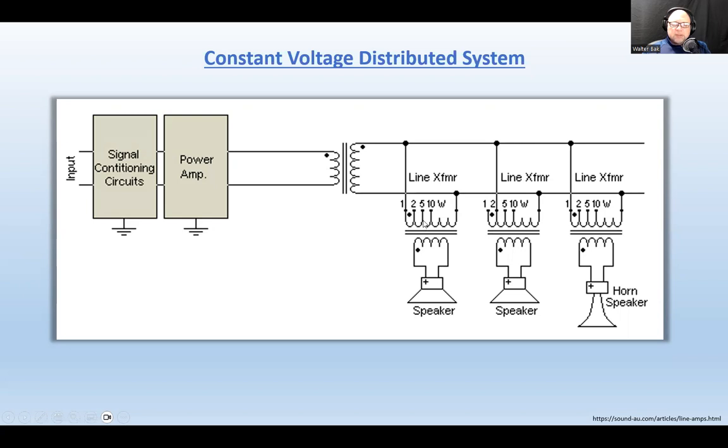What does it mean that those speakers are in phase? Well, you have to have more than one speaker for that to accomplish in phase or out of phase signal happening. Well, if it's a positive cycle of, let's say, a sine wave or a signal, whatever the audio signal is, and let's say the windings are connected in a way that during that positive cycle of the signal, the membrane of the speaker is going to push out.